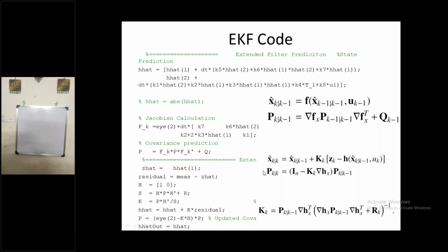In general, by default, the Kalman filter has some tendency to deal with the sensor dynamics. In general the sensor is first order; you can approximate the sensor with the first order, or in some cases up to the second order. If you consider Moog actuators or Moog sensors, they have a frequency of around 100 hertz. That means in 1 second they can give you 100 samples of data. And in its naive form, this Kalman filter can deal with that.